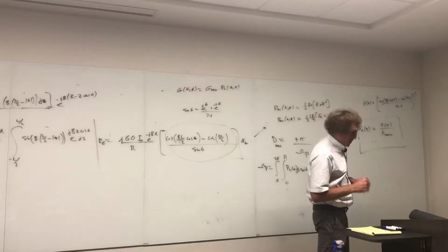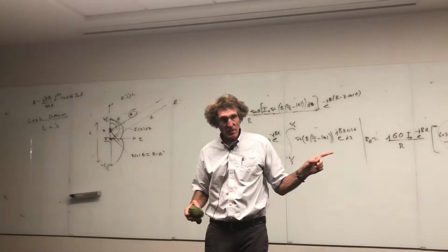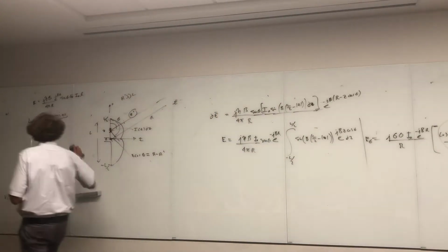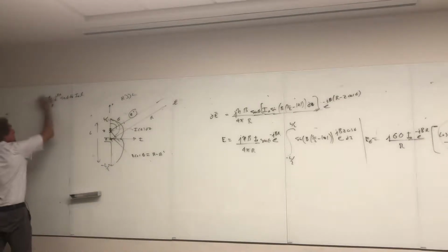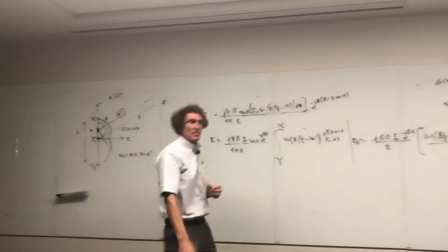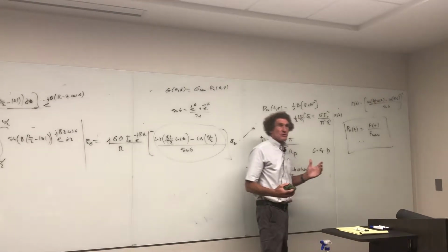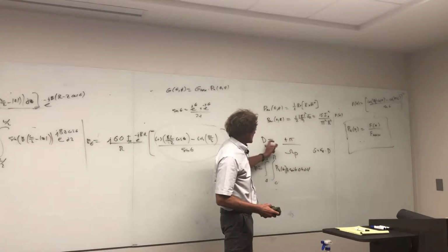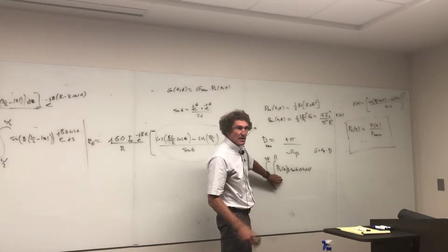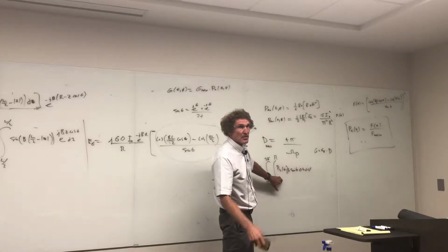All right, now that we have that, radiation resistance I'm going to mention too for this antenna. And these are things I got to tell you about. For an arbitrarily long antenna, let me go back here for a second. If you have an arbitrarily long antenna, there is no closed formula that you can use to get directivity. You see this integration right here? That is not something that generally has a closed form solution. You have to use a computer to do a numerical integration.